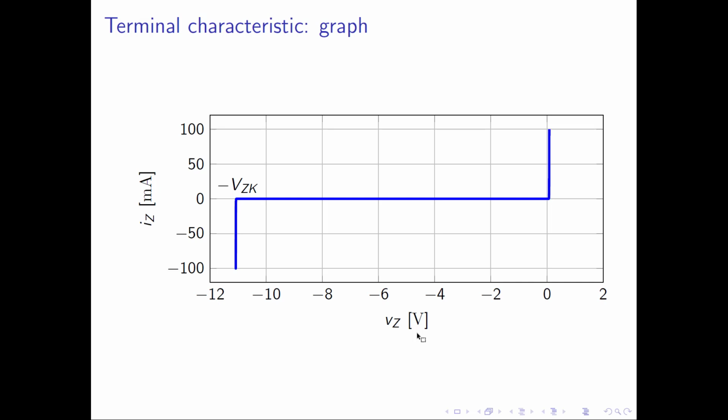And so one of the main applications of the Zener diode is to connect it up specifically in reverse bias and then use the very small variation in the Zener voltage as a function of Zener current to act as a voltage reference.